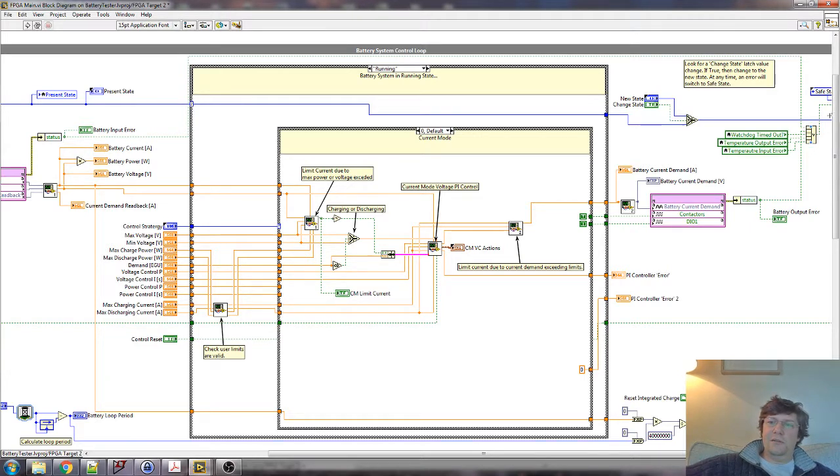A lot of this stuff I did when I was a postdoc, and we were working on testing of batteries for hybrid automotive applications, as part of a suite of CO2 reduction technologies. I spent a lot of time testing batteries, especially doing lifetime testing and trying to elicit pseudo-random binary sequences to measure system properties, or do system identification, by looking at the noise the battery had on its terminals and using that to infer a model of its internals without having to resort to too much electrochemistry.